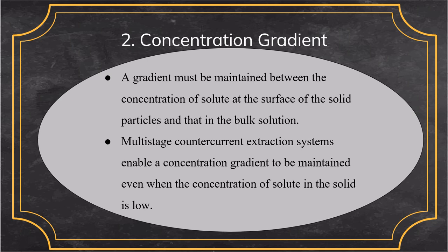But a multi-stage countercurrent extraction system enables a concentration gradient to be maintained even when the concentration of solute in the solid is low. This results in more complete extraction as compared with that attainable in single-stage or multi-stage concurrent systems.